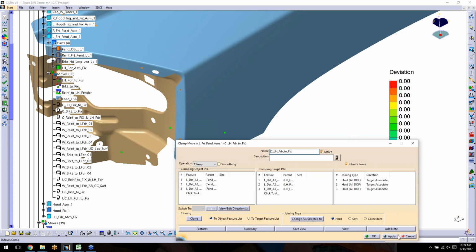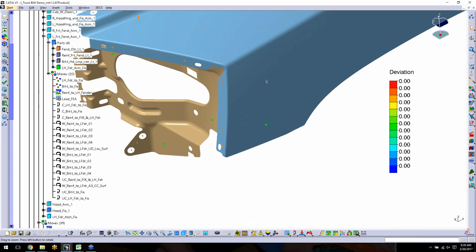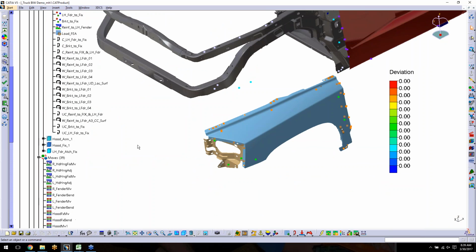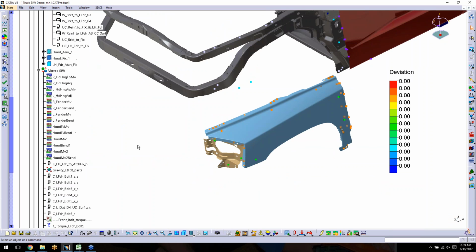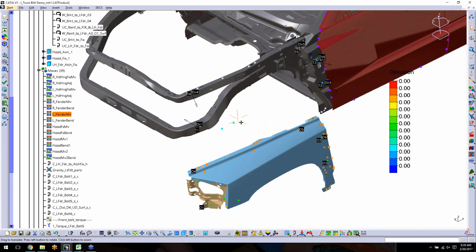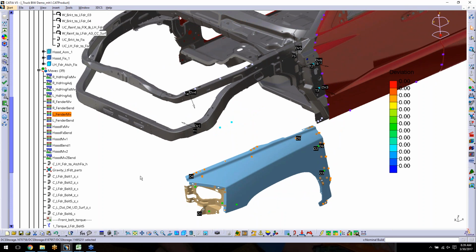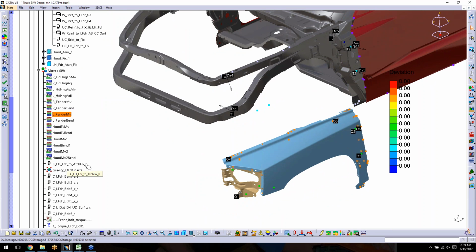Sure. All right, so that would be the fender subassembly. And I'm taking that subassembly and attaching it with a rigid move to the body. After the rigid move, I'm going to use the fender attachments I used before. This is part of the best practices, coordination of datum and locators, right? Same 3 locators I'm using to hold this assembly now into a new fixture relative to the body.